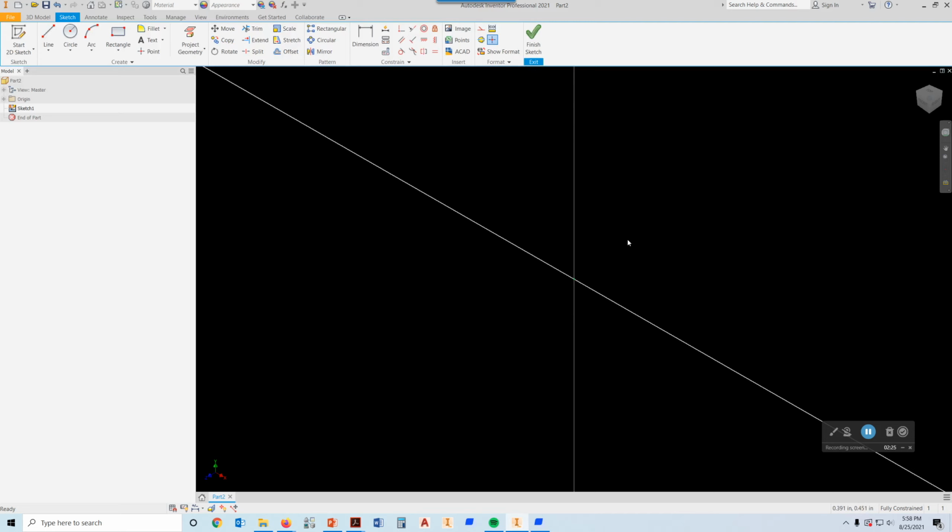All right, but I think it's important in Inventor that we add a little more geometry to this, because right now, if I'm trying to locate geometry from that line, I can't dimension just to this line or just to this line. They're just sort of on there as markers at this point. They're not really set up as an entity that I can dimension from. So here's how we're going to fix that.